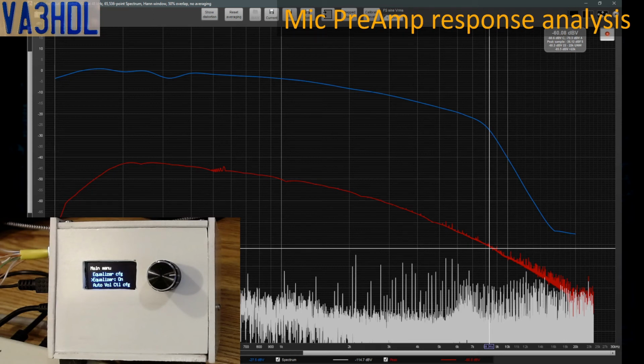So what the equalizer does is not only create a passband from around 150 Hertz to approximately 3.3 or 4 kilohertz, but it also lowers that entire passband level about 20 dBs. So what this does is create headroom for increasing the gain at specific frequencies.